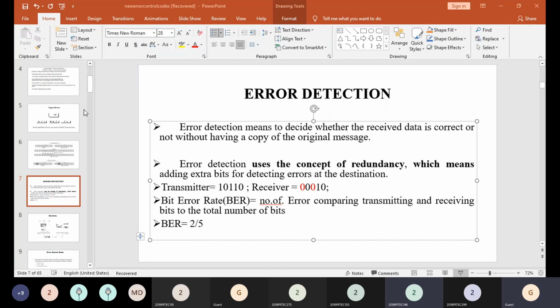So if you take k bits as input, they are constructed into blocks. They are then appended with the generator polynomial, and then the code word is found out.